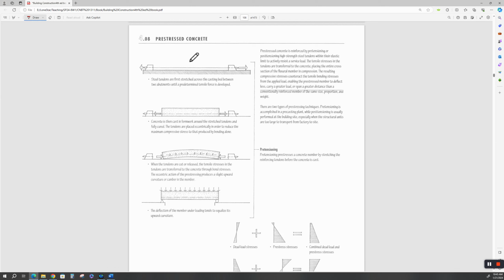All right, pre-stressed. That means that the steel, the reinforcing steel, for a lack of a better word, is stressed before the concrete's poured, okay? So we're pre-tensioning it. I've got some videos that I am going to put on D2L. I've already got them pulled off how this stuff works, post-tensioning and pre-tensioning. There's pluses and minuses for all this stuff, okay?